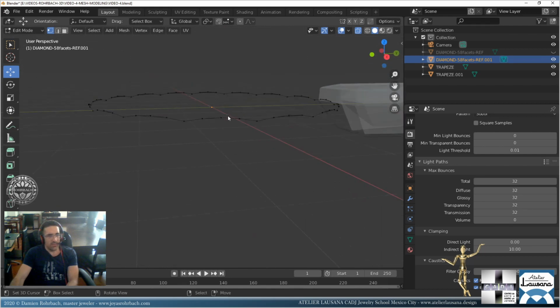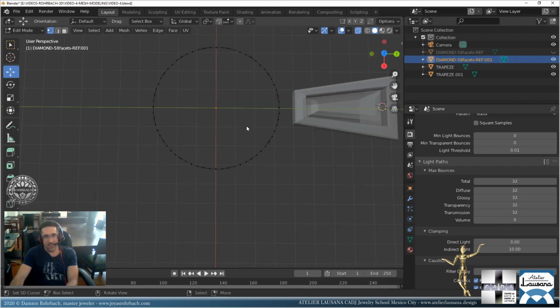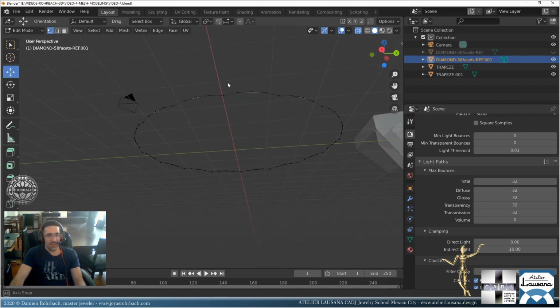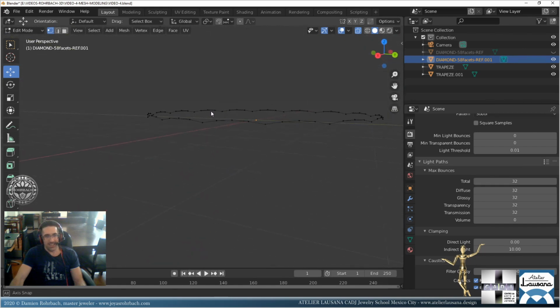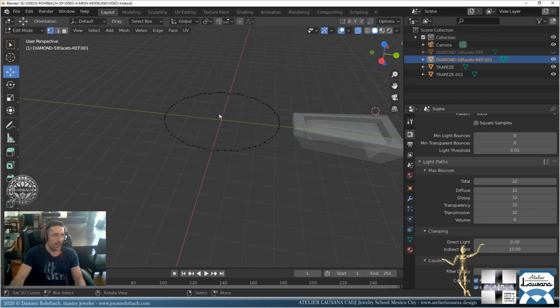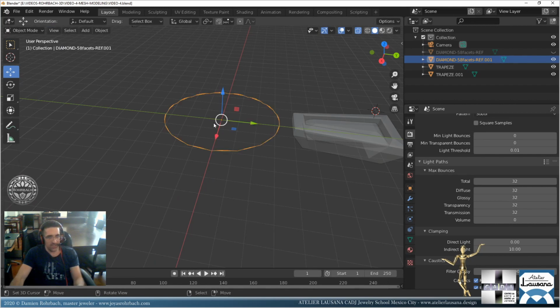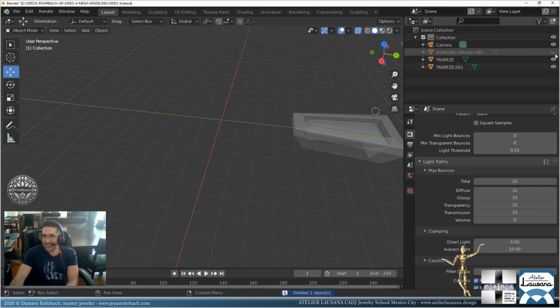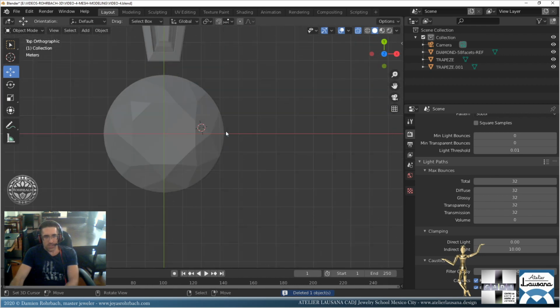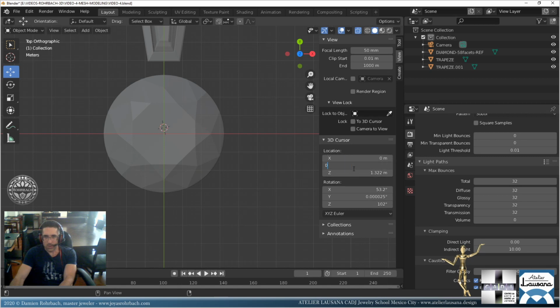Okay, we have this, but honestly, I said we are going to use the same process and principle, but actually we're not, because the vertices we're getting are not so leveled. So let's go out of this. Let's remove this. And let's put the cursor right in the middle there. View, 3D cursor position. Let's put it directly there in the center, totally at 0.